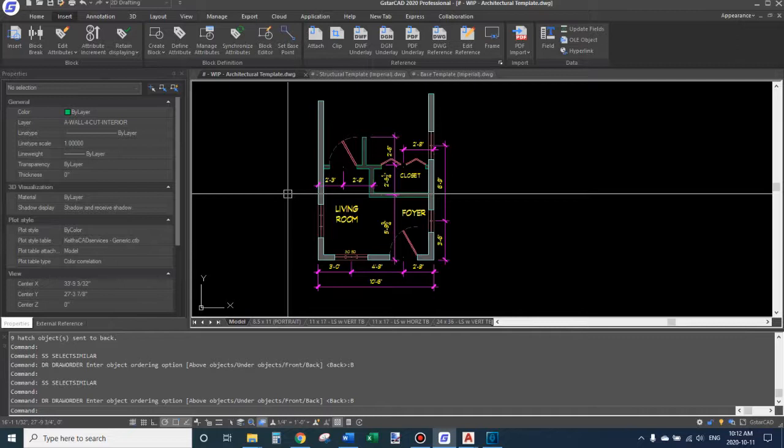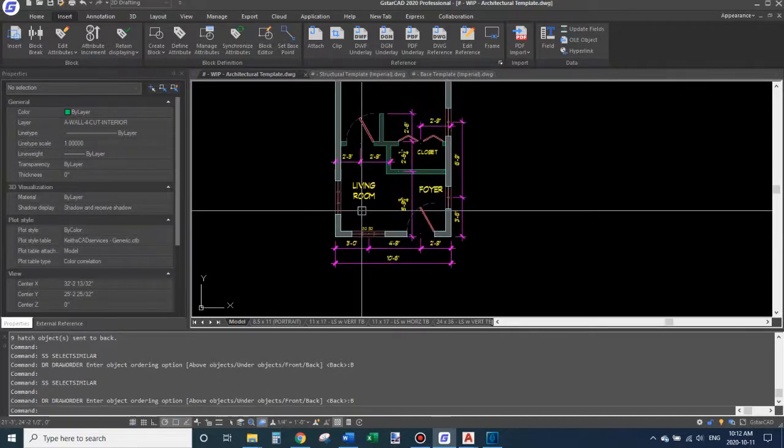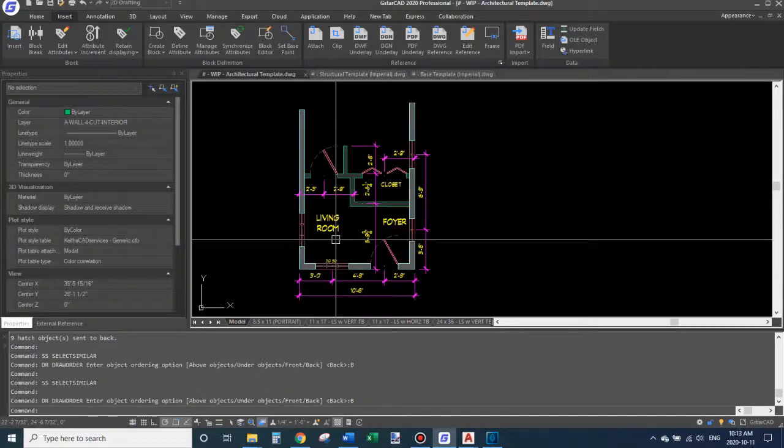Let's say you're going to spend a total of like 50 to 100 hours on a project. Having a PDF file slowing your CAD files down will actually cost you time in the long run. So yeah, that's one benefit. I mentioned the raster converters don't usually work too well. So that's another reason you might want to trace your PDFs. So my strategy is to make tracing the PDFs go as quickly and smoothly as possible if we have to do it. So maybe in the coming years, maybe machine learning will catch up and actually do it for us. But for now, I don't think the raster converters are quite there yet.